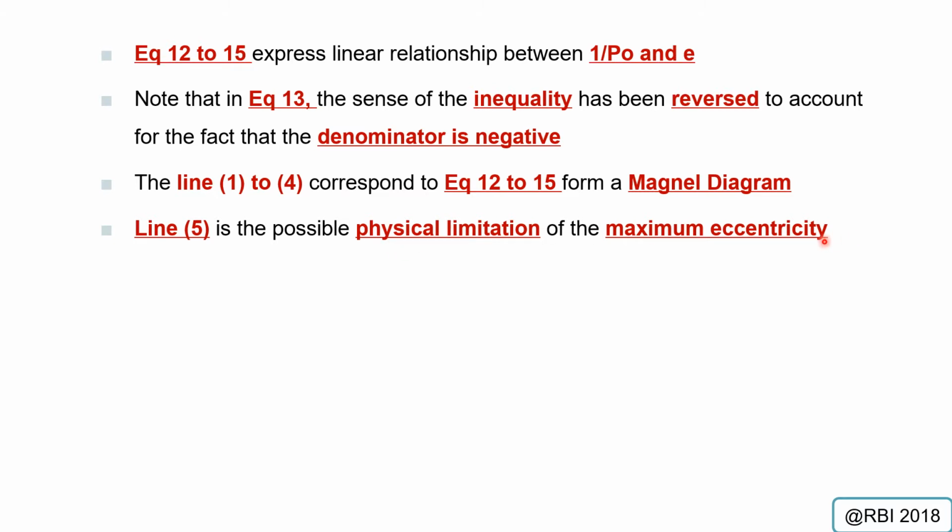A physical limitation is some limitation on the position of the tendon that you want to place, maybe due to your pre-stressed beam cover, or the pre-stressing bed position and so on. It could be any constraint that might occur during construction or during the pre-stressed beam design that you want to carry out.